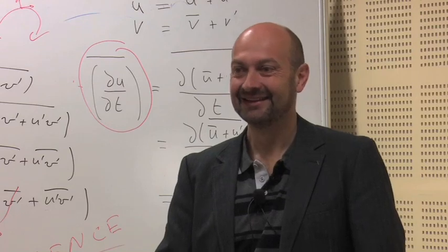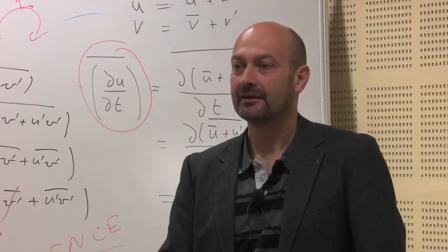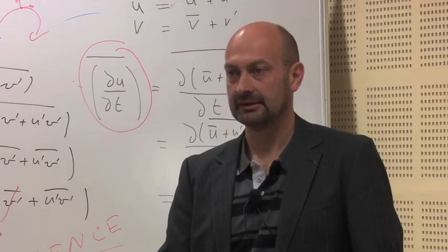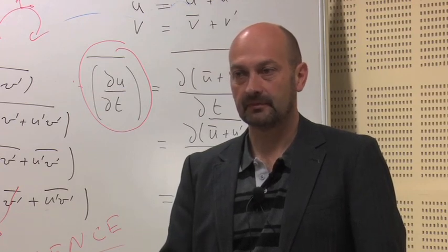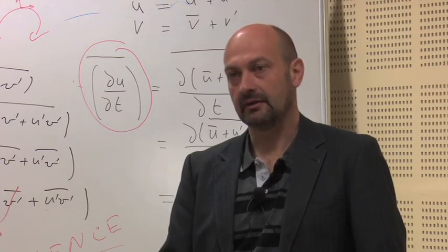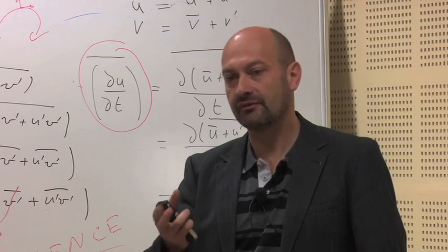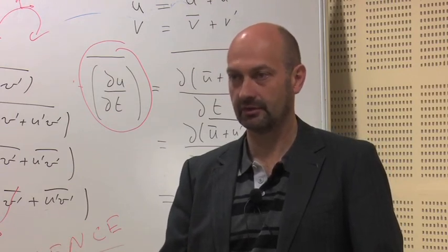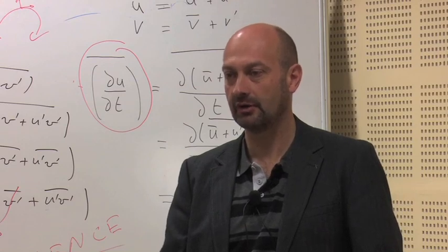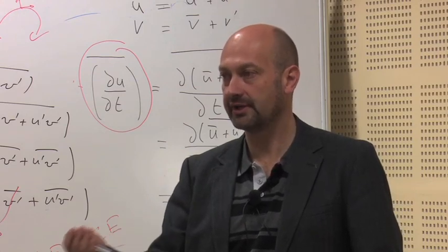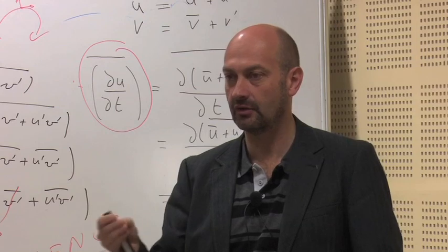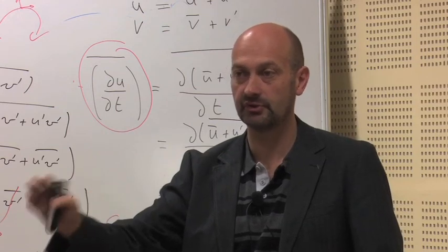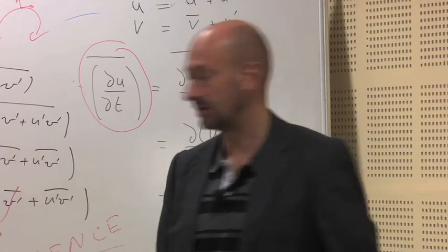Also grid selection, you alluded to something. How do we select when to start, and then do grid independence? Usually this is one of the easy points, because if you have a powerful computer, what you should obtain is, as you mesh finer and finer, at some point the simulation points should not move.